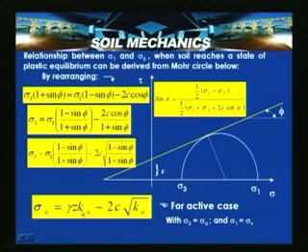Now this equation helps us, for example, for a sandy soil like the physical modeling experiment we have seen in a dry state, where the cohesion is equal to 0. In that case the pressure equation is nothing but sigma A is equal to Ka gamma z.